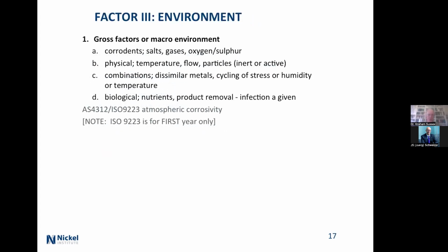What's the environment? Well, what are the corrodants? What salts are there? And I don't mean just sodium chloride. What gases are there? What fumes and so on? Sulfur dioxide coming off burning coal, or hydrogen sulfide coming from a sewage plant. The physical things, how hot is it going to get? Because if it's going to be above 60 degrees C and you've got austenitic stainless steels, then you might worry if there's chlorides around about cracking.